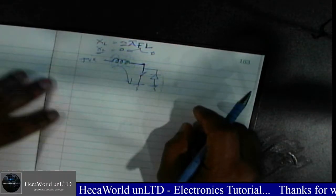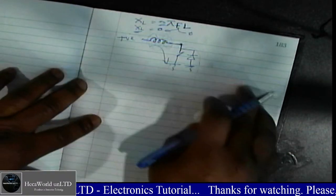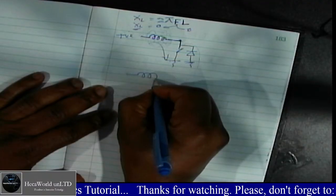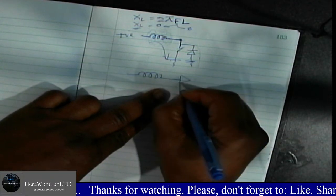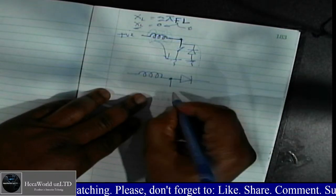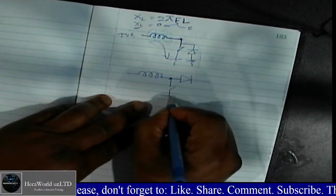And so I'm going to show you how we use this theory, this phenomenon, to generate a DC to DC converter. So what you're going to do is, if I have an inductor, I'm going to have a diode here, and in the middle of this diode and inductor, I'm going to have my switch. So I'm going to just put a switch, and then I'm going to ground it.